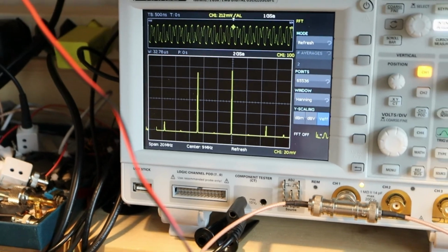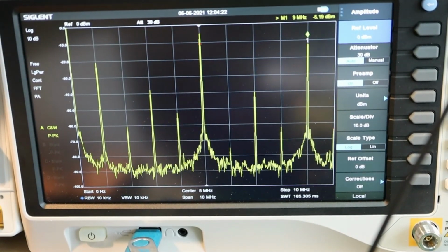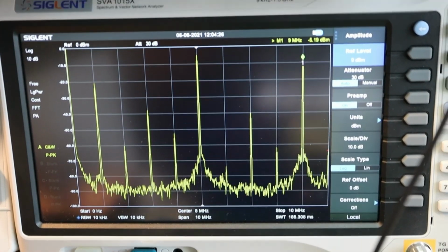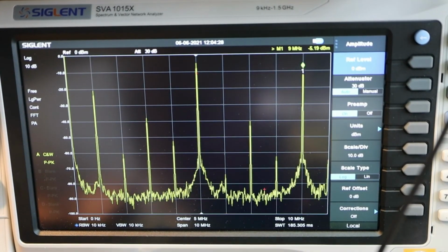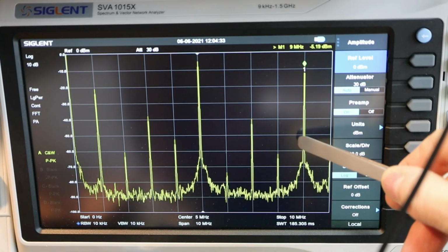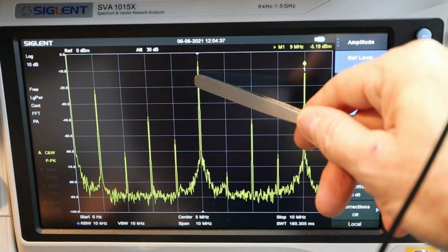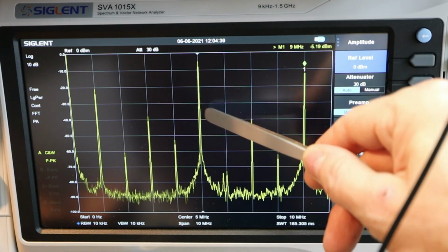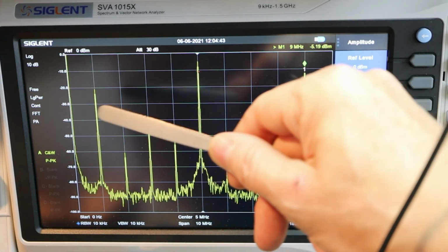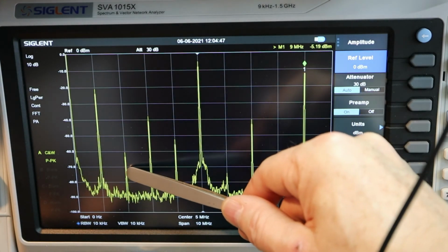So it's much nicer to take a look at this signal on the pretty good real spectrum analyzer in my Siglent here. And you see this same again. You see this 9 megahertz signal, that's what we really want. And you have a 5 megahertz signal down here. And this is 5, 6, 7. So that's the input. And you have 0, 1, 2 megahertz, that's the LO.